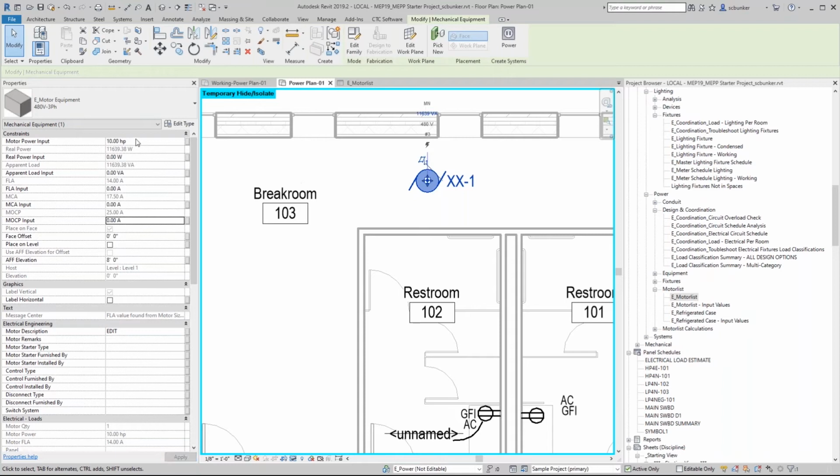This in particular also does linear interpolation. So for the three-phase table, I think it skips from 10 to 15 horsepower. So if I put in, say, 12, yeah, 14, and now it's 16.8 amps. And you should find that that's a linear interpolation between the values between 10 to 15 amps. So this will do that for you, and you don't have to do that manually anymore or using your spreadsheet that you have surely created for your own use.